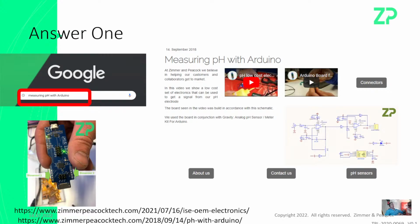So the person wants to measure pH, initially it was pH, in a bioreactor in an Arduino environment. pH sensors are fine, we've got them on the website. Arduino's fine, we've done it ourselves, other people have done it. Your biggest challenge is really getting that pH sensor into your reactor. It's the whole fittings part, because you have to get the sensor into the solution, but you don't want the solution to get out of the reactor, and you certainly don't want it to get onto the electronic connectors. And if you do get stuck on the electronics, we do have a low-cost OEM solution that's probably worth taking a look at.